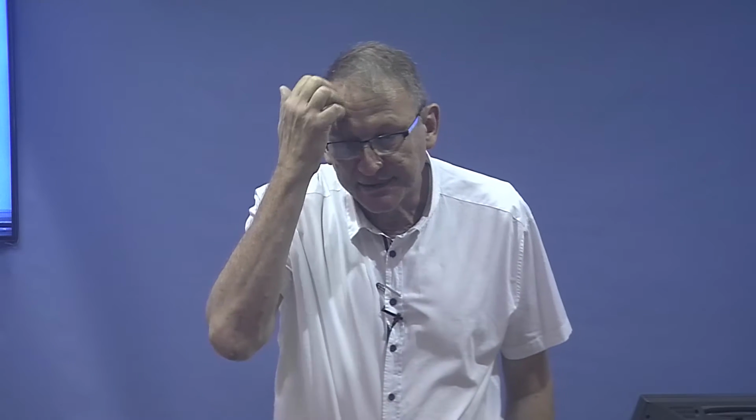Otherwise, you'll get a disturbance on your flow, which will be significant. It changes the flow, and then as many calculations as you make, you are working on some disturbed model, and that's not what you are looking for. So we prefer to be on the safe side, 60% at most, but if nothing else can help, we work up to 70%.